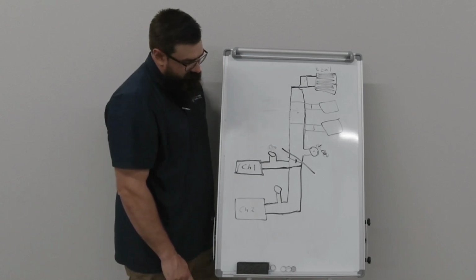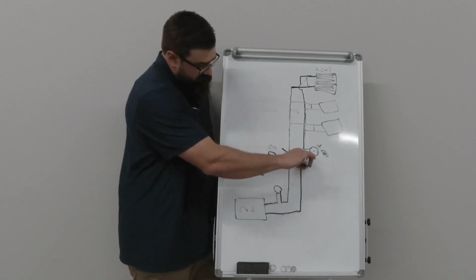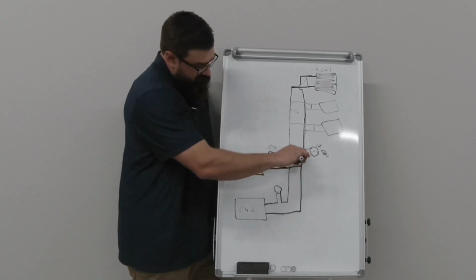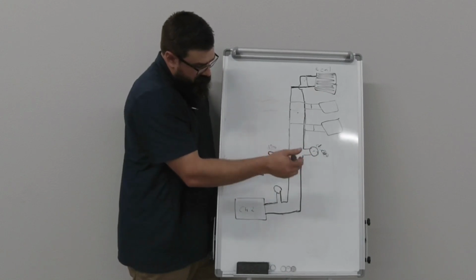What else on bypass valves? One of the tricky parts about when we have a three-way or bypass system versus just a two-way with a speed control and pump is the balancing becomes beyond critical.